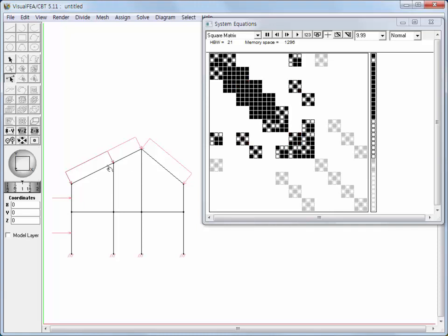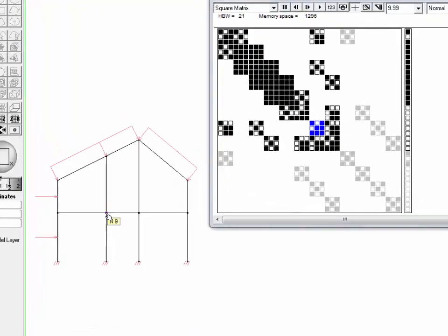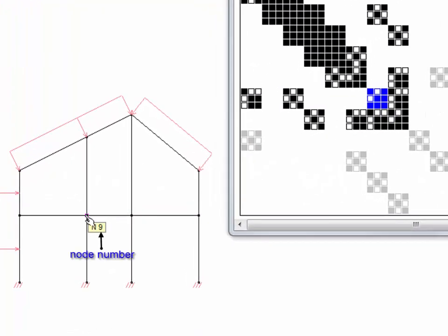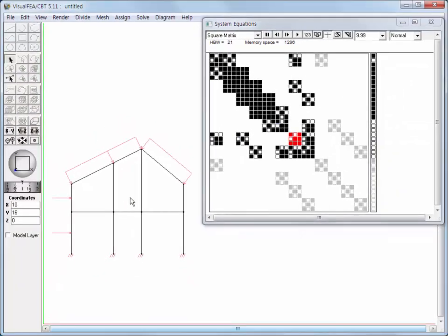Place the cursor on the image of an applied force, then the entries of the force vector, assembled with the element force vector, are highlighted in blue color. Clicking the force freezes the highlight of the entries in red color. Press Node Selection tool button, and place the cursor over a node. Then, the node is marked by a small red square, and all the entries related to the nodal degrees of freedom are highlighted in blue color.